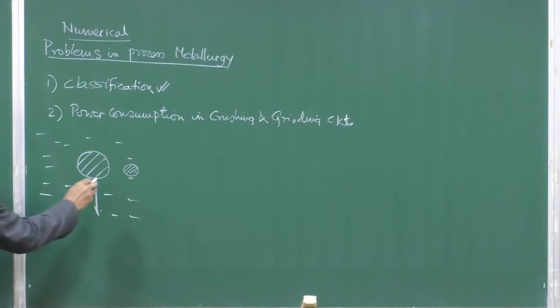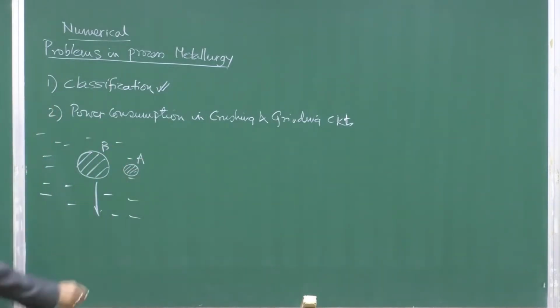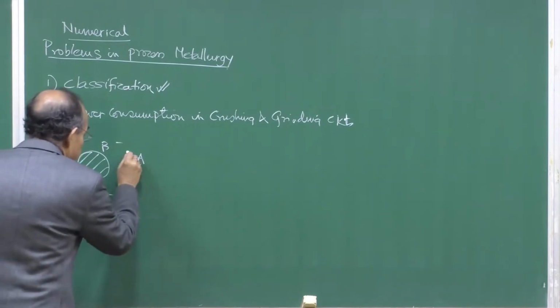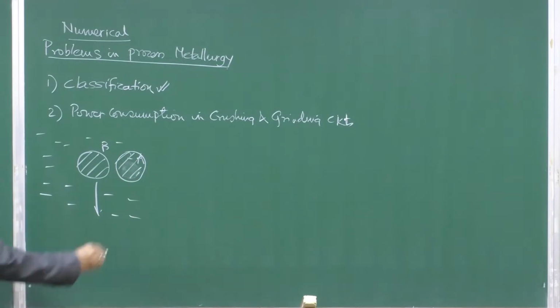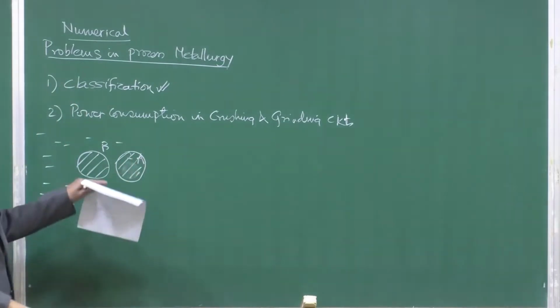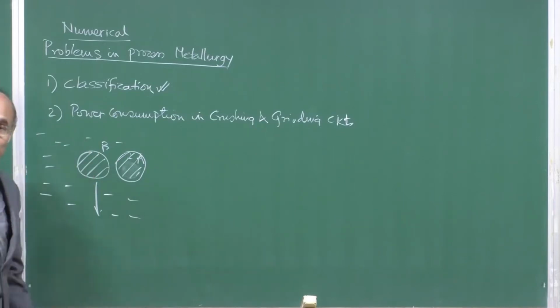In the same fluid, if you have material A and material B, and you say that the sizes are more or less equal, then if the particle density of B is greater than A, the particle B is going to settle down faster. And these are basically, in the context of stagnant fluid, derived from Stokes law,